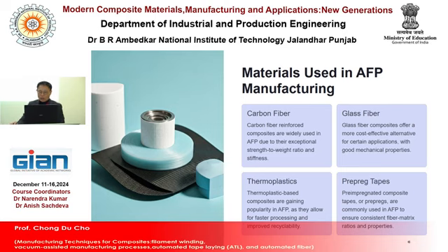And for layup strategy and optimization, fiber orientation, layup sequence, and compaction force can be controlled automatically by the AFP machine. For inspection and quality control in AFP, in situ monitoring is possible, dimensional inspection is also possible, and non-destructive testing is possible on-site. Right?